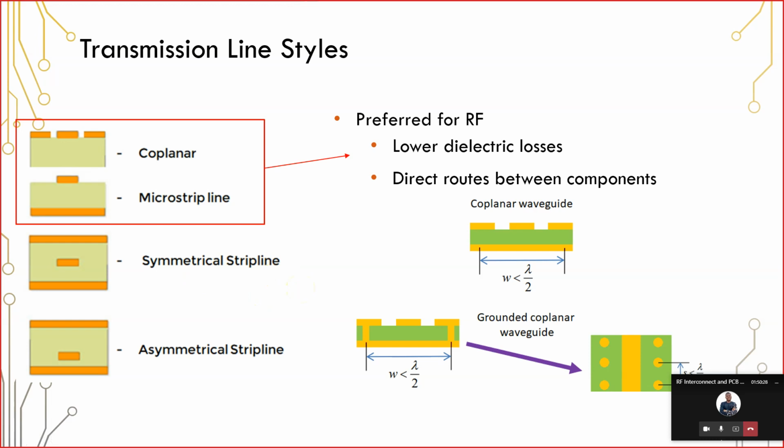However, as I mentioned before in the 8-layer stackup I showed earlier, you can do strip line routing for RF signals. And in fact, we were doing it at 20 gigahertz. So that just illustrates that, yes, you can in fact do this.